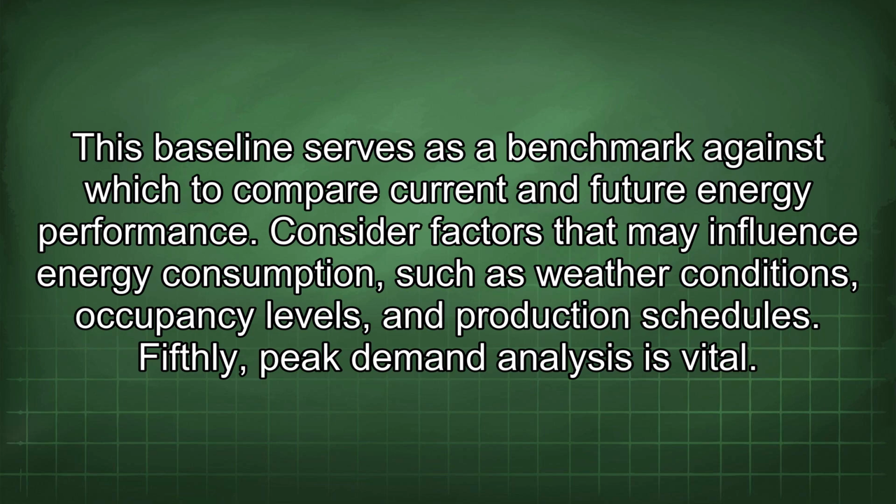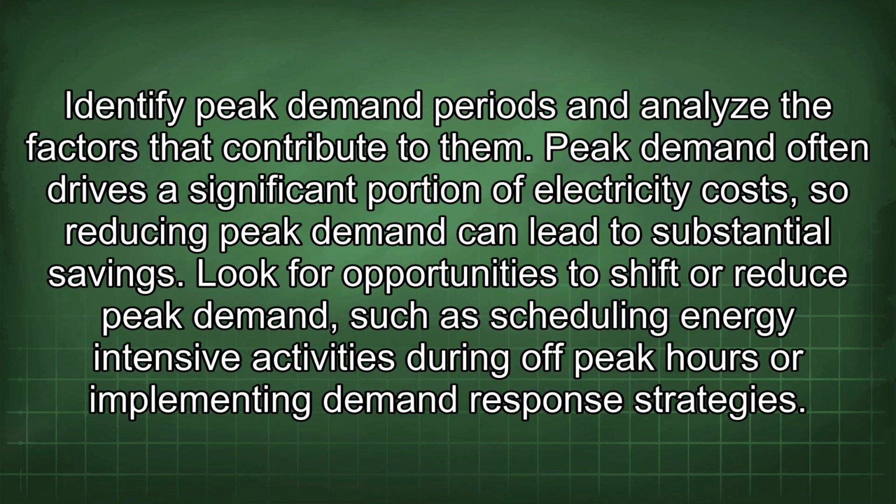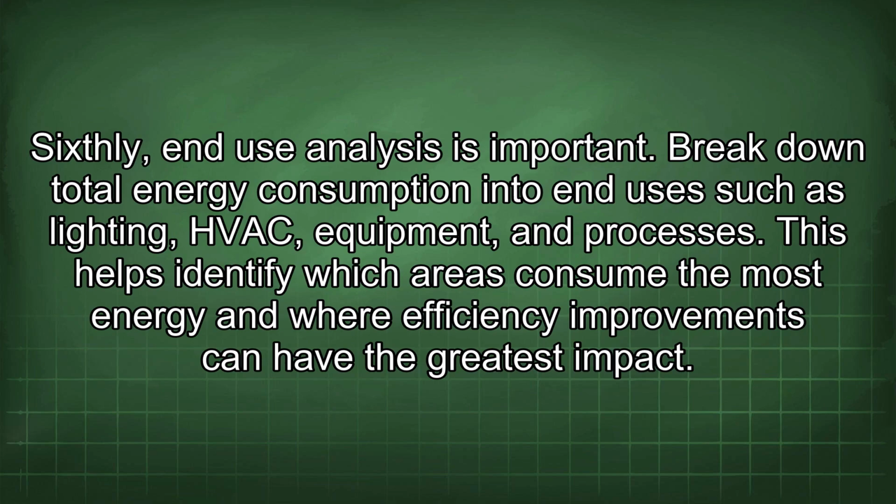Fifthly, peak demand analysis is vital. Identify peak demand periods and analyze the factors that contribute to them. Peak demand often drives a significant portion of electricity costs, so reducing peak demand can lead to substantial savings. Look for opportunities to shift or reduce peak demand, such as scheduling energy-intensive activities during off-peak hours or implementing demand response strategies.